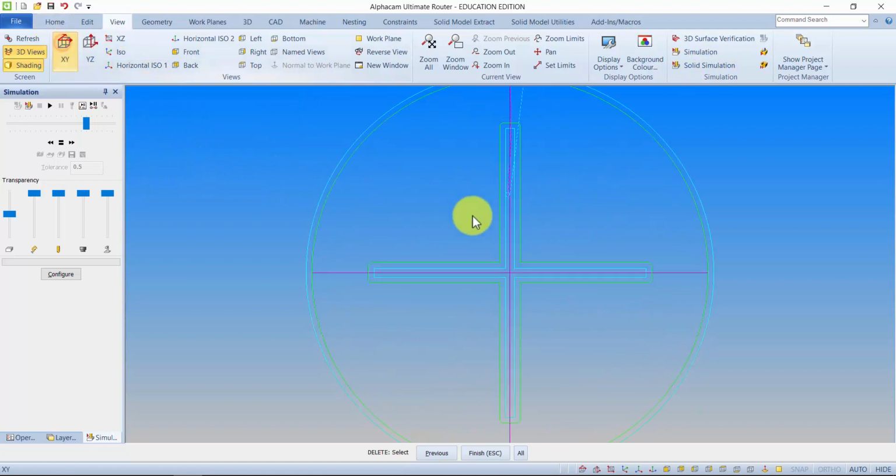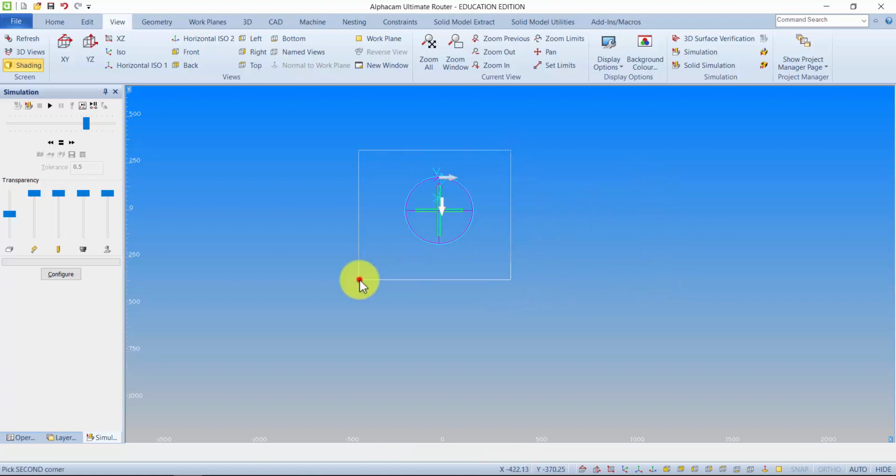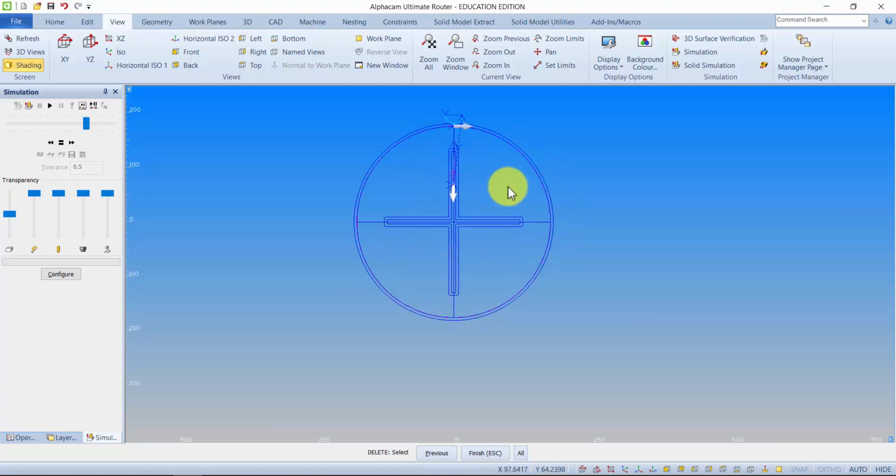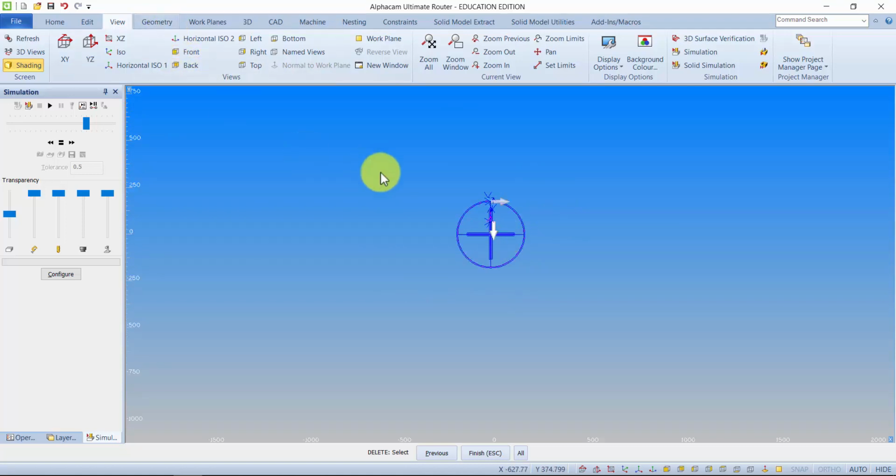So moving back to XY, what I want to do to finish off this stool is get the geometry and the machining applied for the top, for the leg, and the lock key all in one file, and then I can just take that and copy and paste or pattern it or nest it onto a sheet as I see fit later. So once the geometry and the tooling is done, you have the majority of the work done for the components. You can use them over and over again. There's certainly no need to go drawing the blocks and saving the blocks of timber around them.